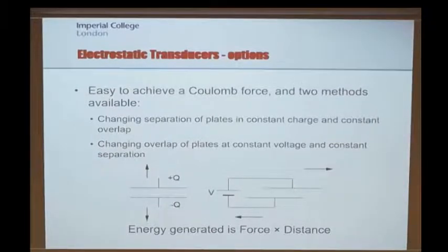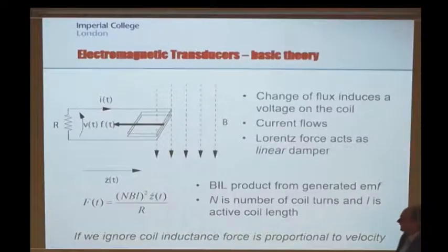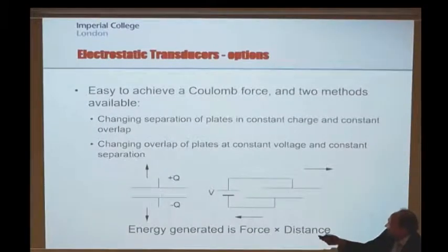Air damping is going to be something that is, well, maybe quite complicated to model, but is often modeled as a linear damper, as this type of scenario where the force depends on the velocity. In this scenario, the force does not depend on the velocity. There's simply a constant attractive force between the plates. And that's true also in the sliding type of approach, where we take the plates and we slide them across each other, as long as we operate the system in a constant voltage.